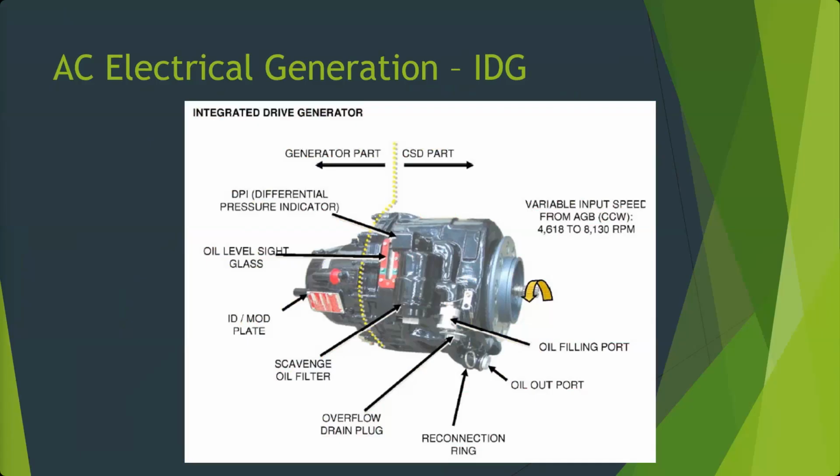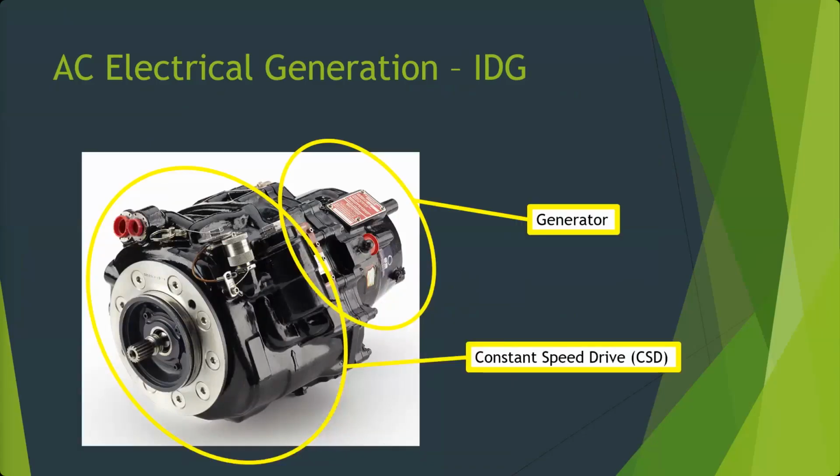Somebody forgot to pull the plug from the standpipe before they started pumping oil in. Have you seen it where oil from the engine actually got into it? It really can't. It can kind of get between, but it can't really get into the oil system. So it can't leak past the seal or anything like that? If it leaks past the seal, it's a very small amount. It's not enough to affect the level in there necessarily. So you won't even notice it? Not really. There's where these connect. Let me go back. Where these connect to the gearbox here.